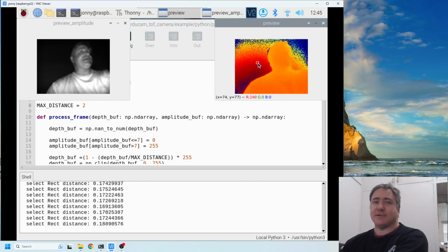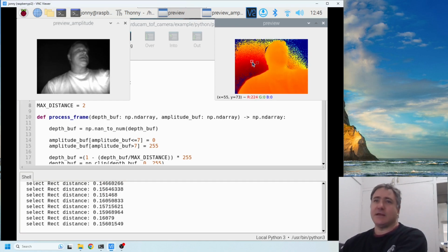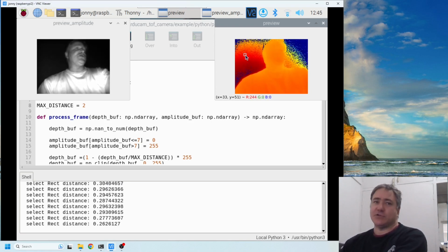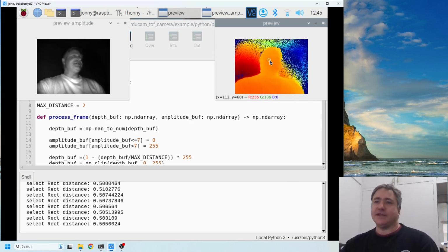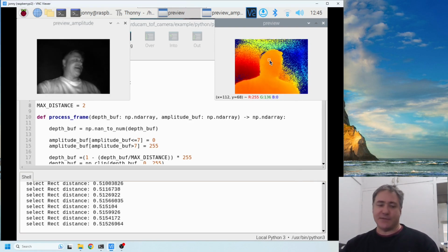So what's happened is it's sent out the pulse, and the pulse is bouncing back, but before that pulse has reached the sensor, it's already sent the next pulse out. So that should be a 2 in front of there. So how can we get rid of that? I mean, this didn't happen when we did the 4, just because everything in this room is more than 4 meters away.